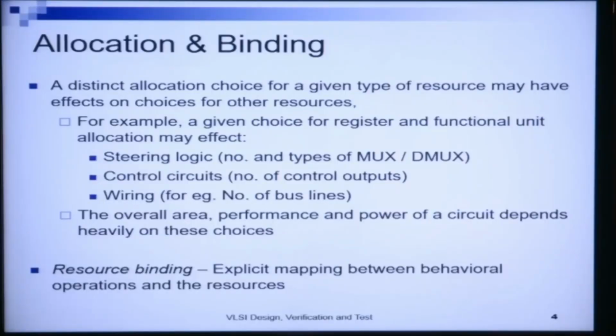The choice of types and number of muxes will depend on the choice of registers and functional units that you have made. It will also determine the control circuits that you have. For example, the number of control outputs that you will produce will depend on the numbers and types of muxes and demuxes.